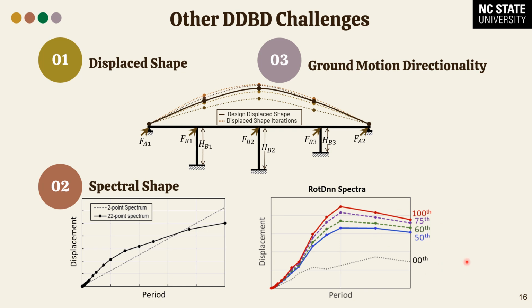And to do that, we need to account not only for the principal directions of the bridge, but also any off axis of the bridge. So for that evaluation of what rho D should be used in design, we need to look at the performance of bridges under multidirectional loading. And with that, thank you for your attention.